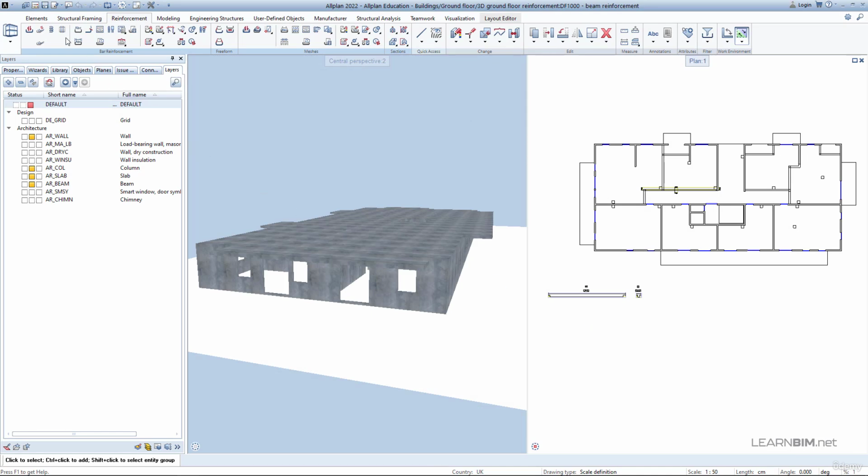After proper placing in the cross sections, reinforcement will also appear in the 3D model. Have in mind that reinforcement cannot be copied from one cross section to another because those are different views. It can only be copied in plane view directly on the model or within the same cross sections. The reinforcement cannot be selected in any other viewport. You can access all the commands for reinforcement in the Engineering module under the Reinforcement tab.